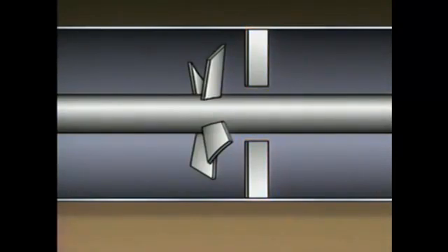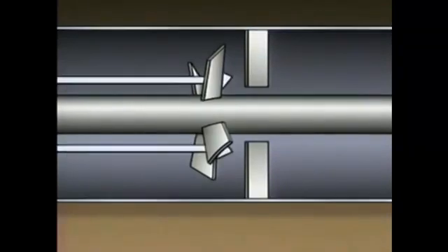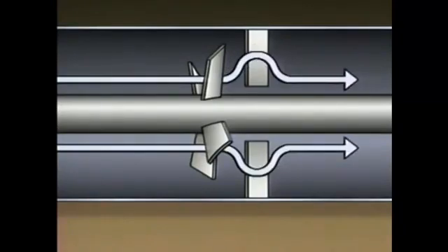During operation, the rotating blades spin like the blades of a fan. They draw gas in and accelerate it to increase its velocity. The rotating blades then push the gas towards the stationary blades. When the gas contacts the stationary blades, they cause the gas to change direction as it flows toward the compressor's discharge. This causes the gas to slow down. As the gas slows down, its pressure increases.